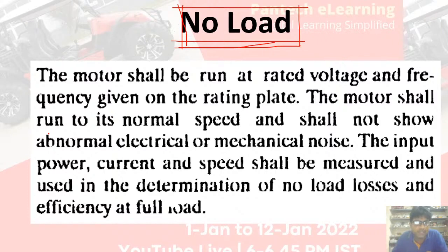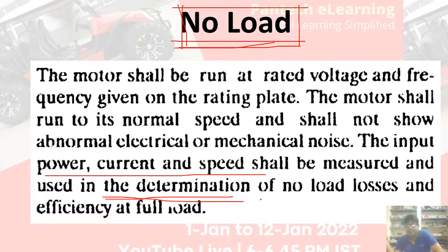The motor shall run to its normal speed and shall not show any abnormal electrical or mechanical noise, and at that time you have to monitor the power, current and speed, which will be required for the determination of no load loss, and this will be needed to calculate the efficiency of the machine.